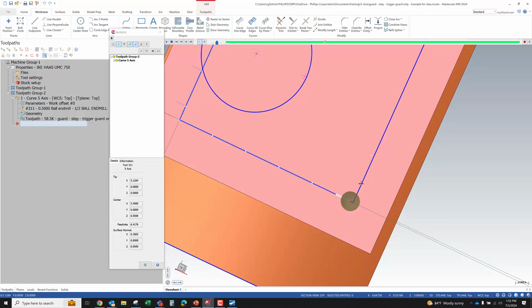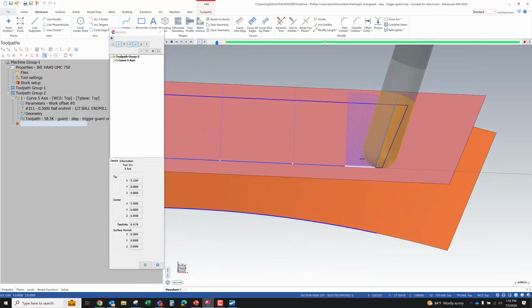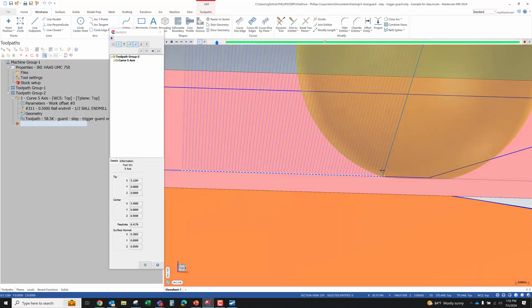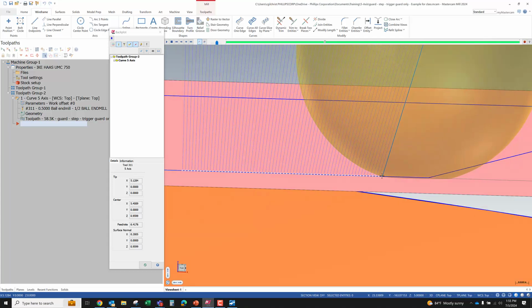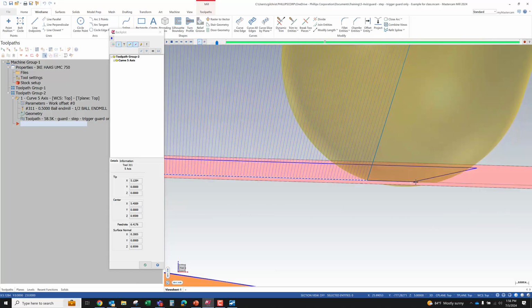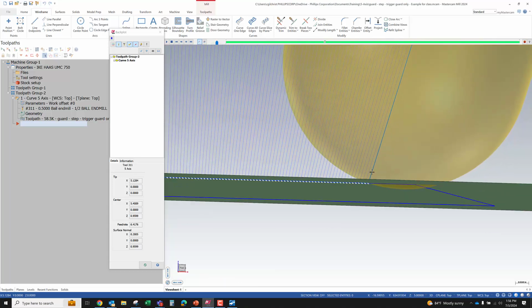We're driving a vector, and the tip of that vector represents the center line of the tool, and we're forcing the center line of the tool to be on the geometry. So the tool vector is different from what we would consider the contact point. The contact point is the point on your tool that is actually tangent to the surface that you're driving it.